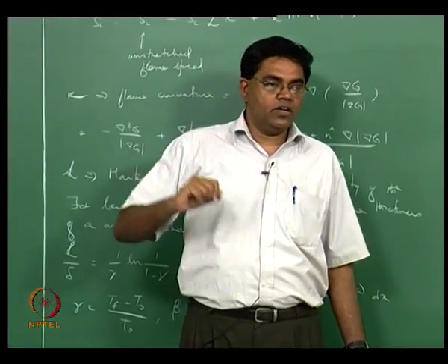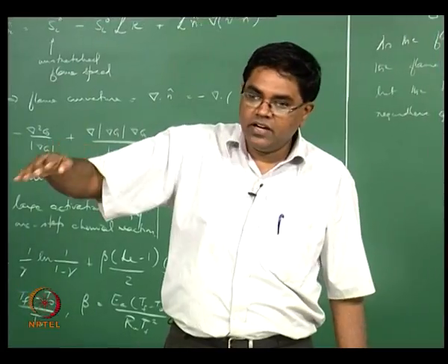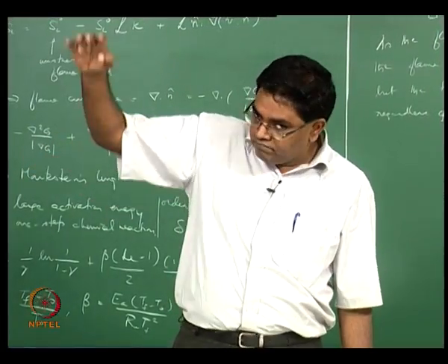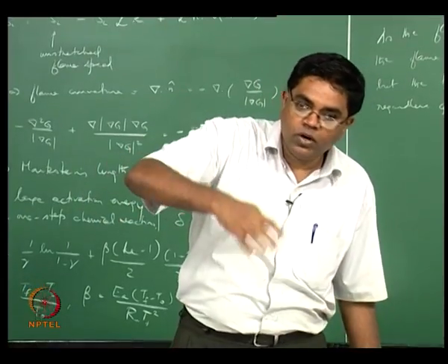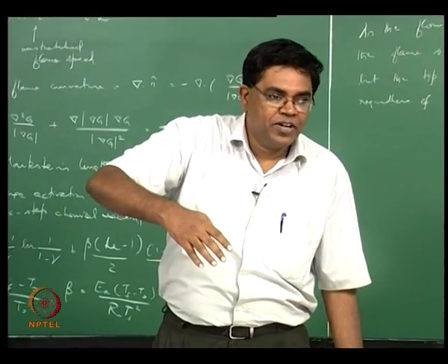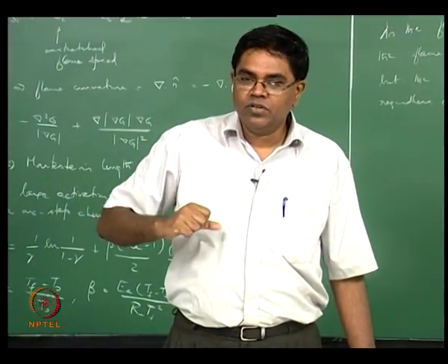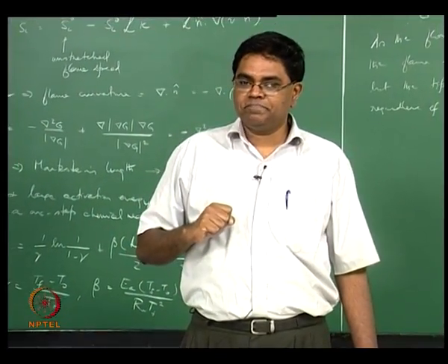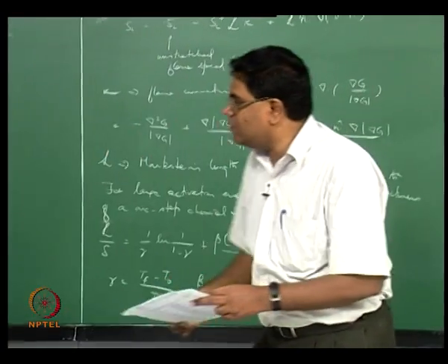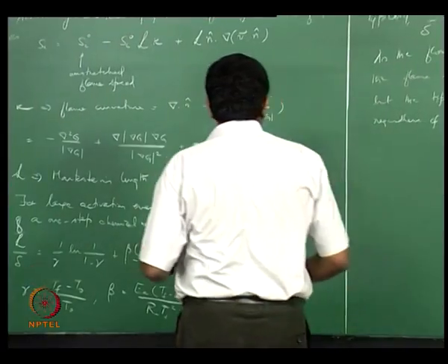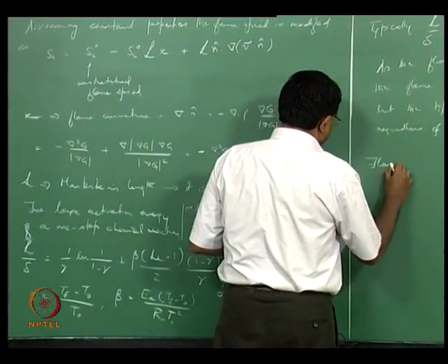On the one hand, it looks like the flame has to actually not be held at the burner at all, and maybe get pushed up by the flow, but if you now begin to look at the flow, it looks like the flame has to go deep in. What's going on? So this idea of having to look at the base of the flame takes us to the issue of what's called flame stabilization.